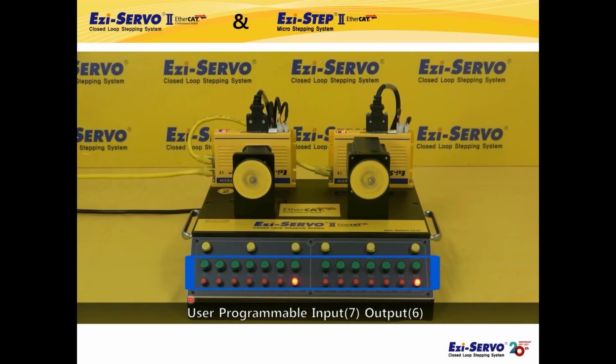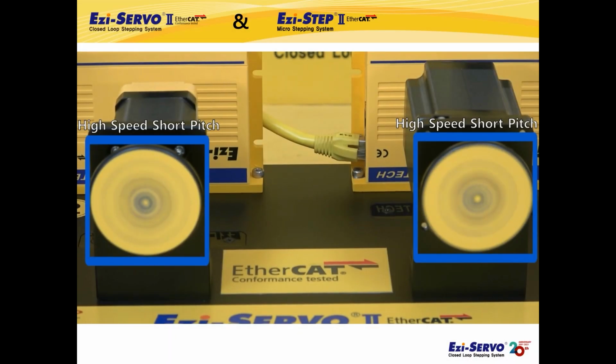Because I/O wiring is done, the user can directly perform limit, origin sensor, break and general input-output tests through the front buttons and LED. Also, it is possible to test the operation according to the operating conditions set by the user through the master. For example, in this demonstration, the master program Beckhoff's TwinCAT software was used to drive 2 axes with high-speed short-pitch motion through EtherCAT communication.